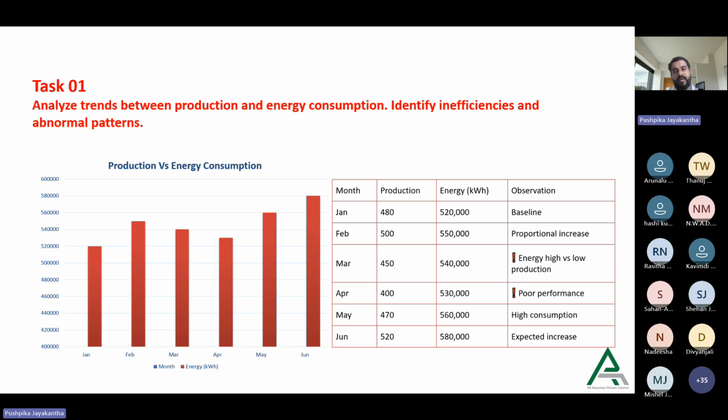This can be due to simultaneous startup of equipment, no demand side management system, no peak time operation and high load equipment management, and lack of staggered operations. So this increasing demand trend indicates inadequate load management practice and results in high peak demand and increased energy cost exposure.